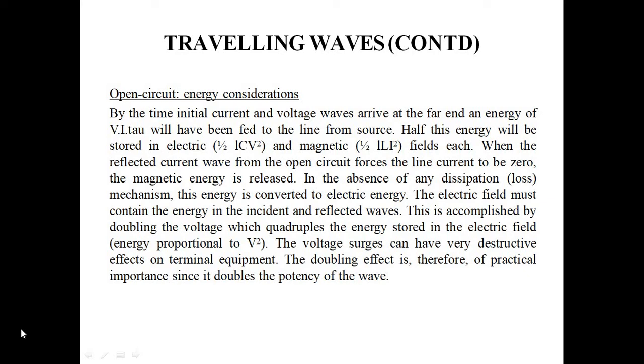This is accomplished by doubling the voltage, which quadruples the energy stored in the electric field. Energy is proportional to V squared. The voltage surges can have a destructive effect on terminal equipment. The doubling effect is therefore practically important since it doubles the potential of the wave.